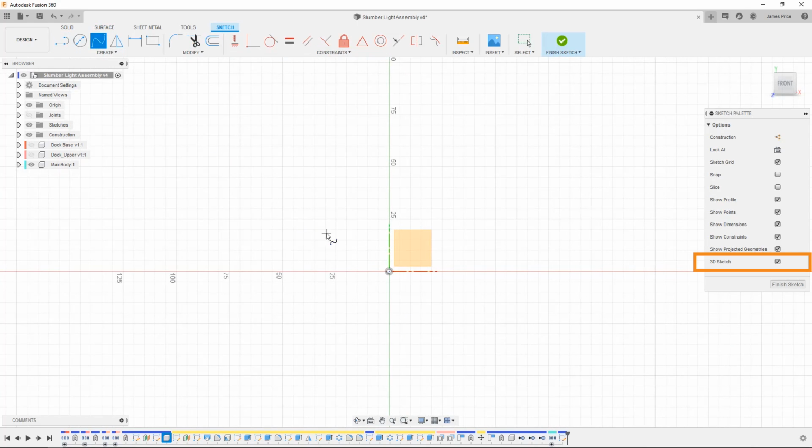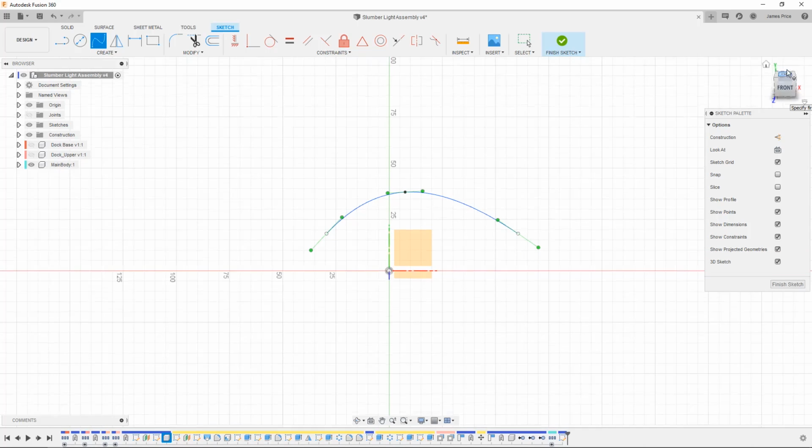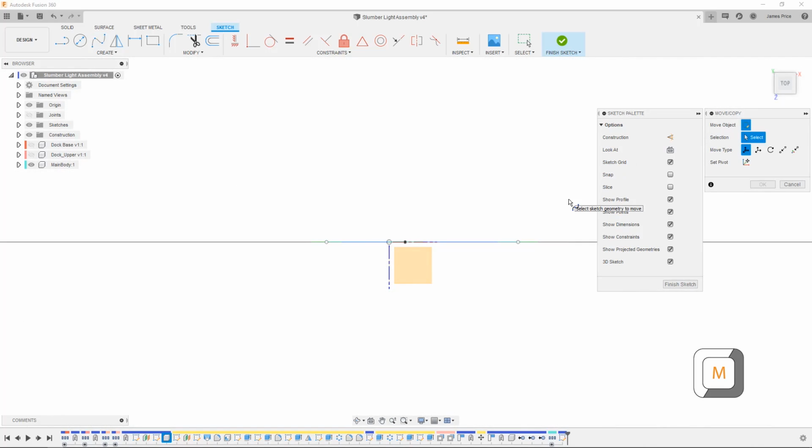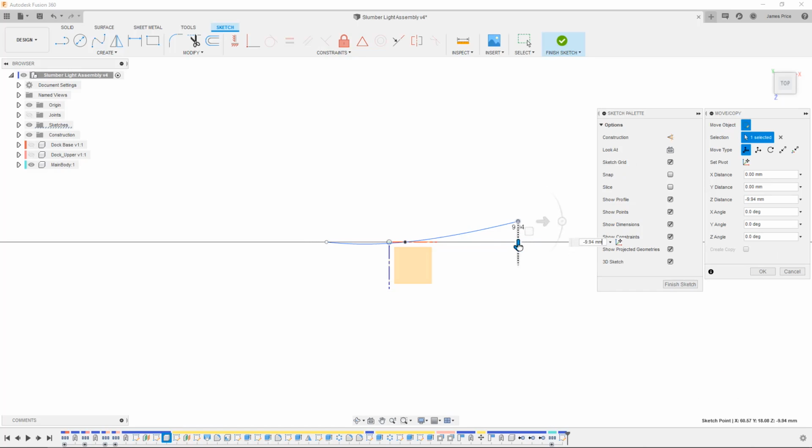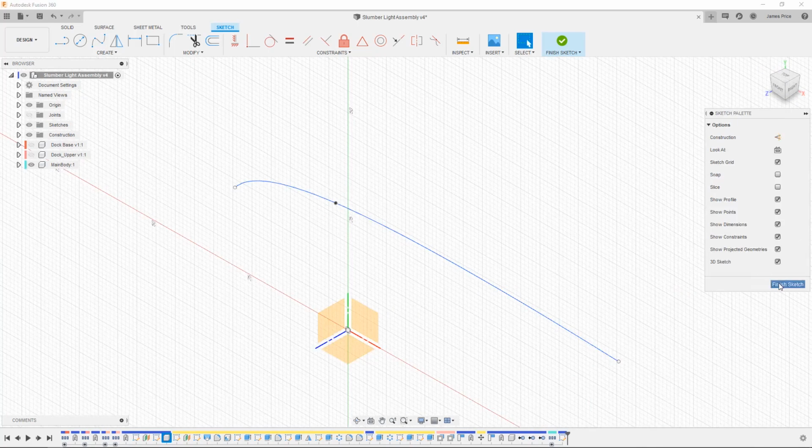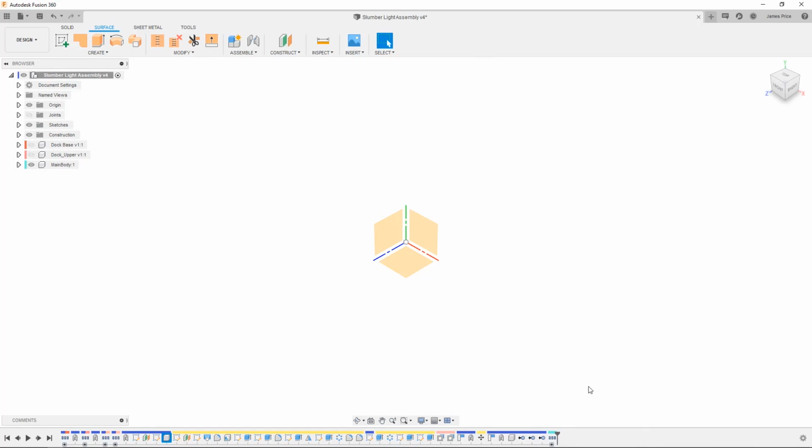You can also enable 3D sketches in the pop-up dialog box, then use the control points to put these into position. Fusion 360's added benefit is that it also utilises T-spline surfacing technology, a more organic approach to help speed up and simplify your surface modelling process, which you will find under the Solid tab using the Create Form command.